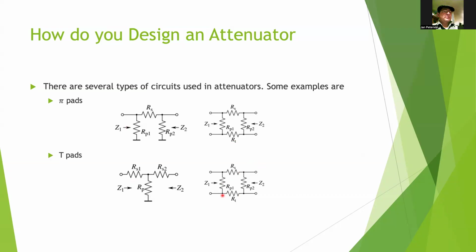And you'll notice that they do a little bit of extra connectivity here to make sure that the circuit stays balanced, that they don't do on this one, okay? And if you look at these symbols here, this is like the input to the thing, and this is the output. And then this is a resistor here. This is the ground. So these are tied to ground. And we run our power through here, and it will bleed off some of our power to ground. And so the power that ends up coming out is attenuated or reduced based on the amounts of these resistors.